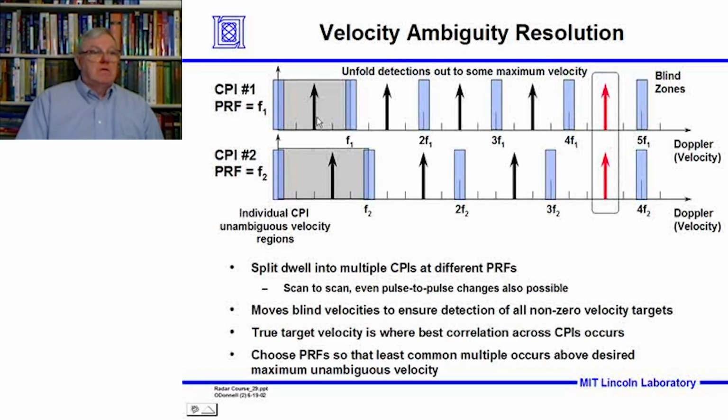And we notice that the Doppler filter that the real target falls in is n times the blind speed plus the residue left over, halfway between 0 and the blind speed, because all of these fold down. And you see it here. In the ambiguous space that you measure in, the target would appear here.